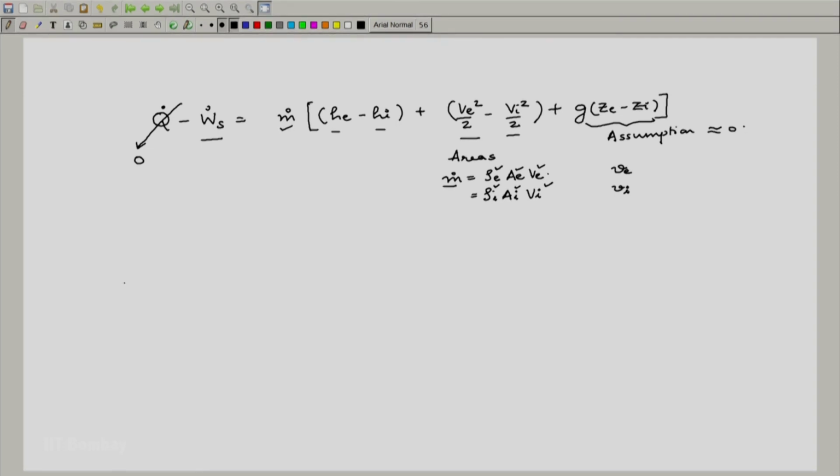So, let us go about doing this. What information do we have? We have at the inlet 3.4 bar, 5% moisture. This means that the dryness fraction is 95% or 0.95. So, x is 0.95, that means the vapor is 95% and the moisture is 5%. That is what 5% moisture would mean. So, x or the quality is 0.95.